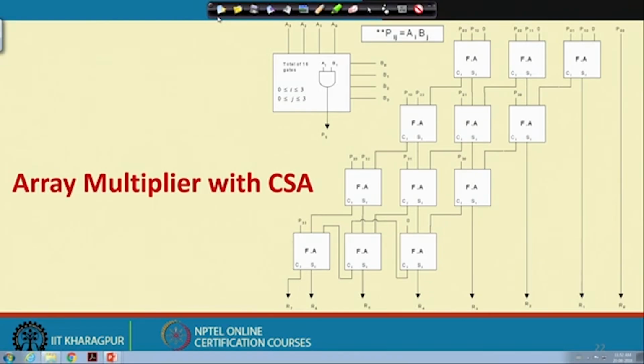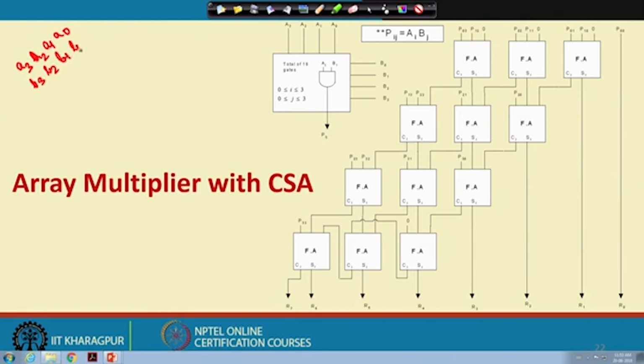So, the same thing I can do if I use a carry save adder. Instead of the carry look-ahead adder, here I will use a carry save adder. Carry save adder means if I just rewrite this equation again: A3, A2, A1, A0, B3, B2, B1 and B0. Then, that means now A3 B0, A2 B0, A1 B0, A0 B0, right.